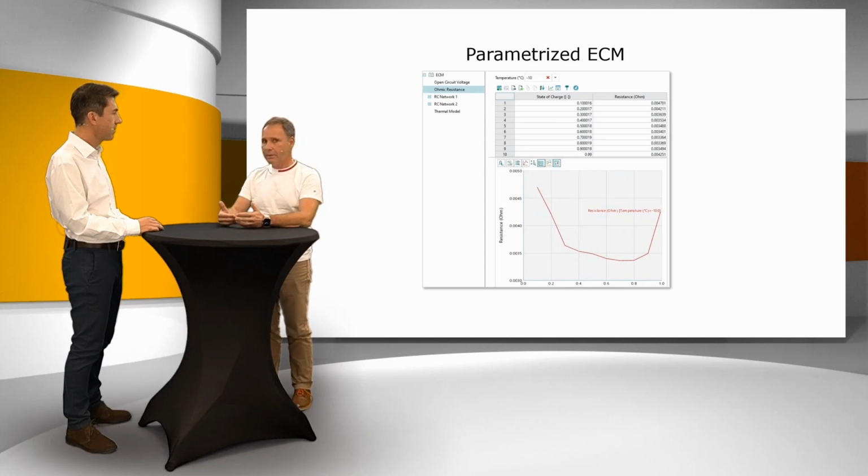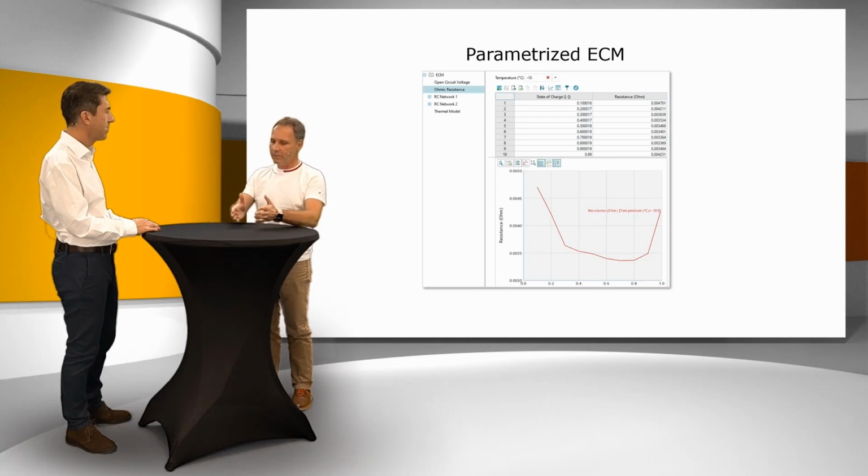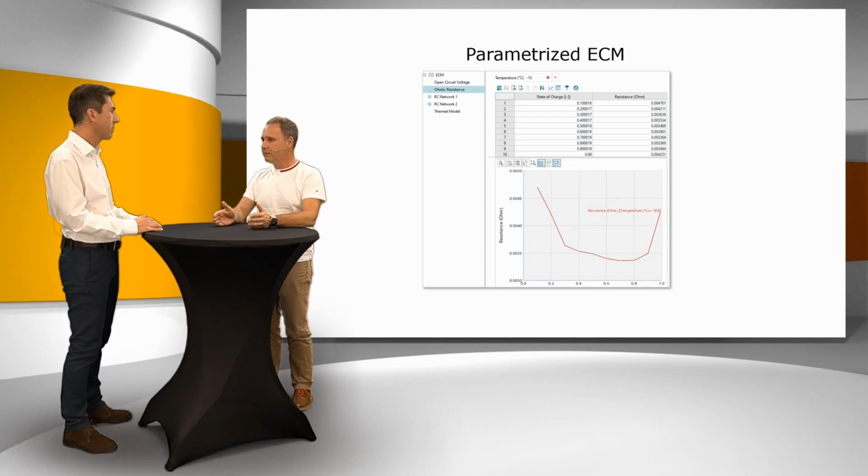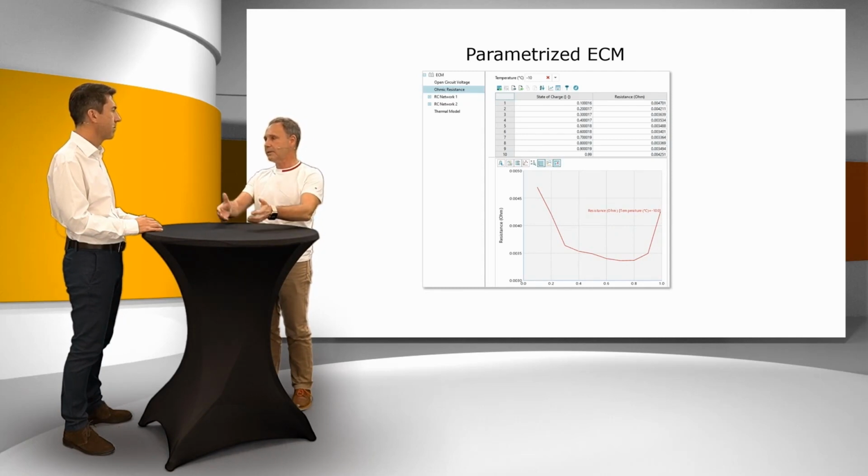So as an example, when you have this HPPC profile, you just cut that in slices. Normally you do that manually. We just have here an automatism that automatically detects all the pulses, all the individual temperatures, reads that in, and is doing this fitting automatically. And with that, of course, it's now much easier and again accelerates the development from, let's say, weeks of testing to maybe a day with support of electrochemical models and automatic deriving of these parameters.